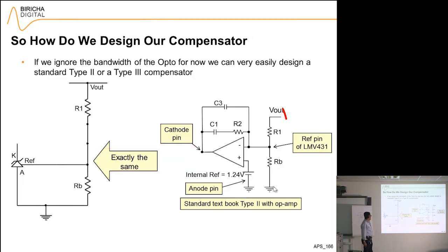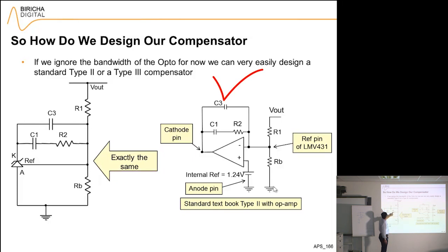So first I will make this potential divider, which is exactly the same as this. Then I will connect the compensation component. Please have a look at this. It's exactly the same as that, and I'm done. When you look at this on the datasheet of a device, it looks a little bit intimidating because you think, where are all of these components coming from? But in reality, that is just that op-amp. So you haven't invented anything difficult. It is just what we have always been doing.